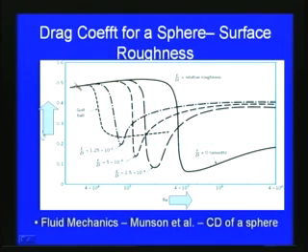If you consider, for example, a golf ball, depending upon the Reynolds number this is the pattern, where epsilon by d is considered, epsilon is the roughness and d is the diameter of the sphere. If the surface is very smooth, then initially the coefficient of drag slightly increases with Reynolds number, and then after the critical range, when the flow becomes turbulent, there is a sudden decrease in the coefficient of drag, and then after a certain range the coefficient of drag increases again like this.